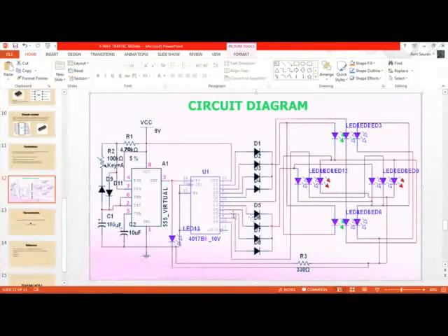And the next pulse will come and pin 1 will be activated, like from 06, 07, 08, 09. These are connected here, you can see, and these are also connected to the two green LEDs, and the next two green LEDs will light up after this yellow LED turns off. At the same time the other two red LEDs will be lit up so that the vehicles can go and pass.